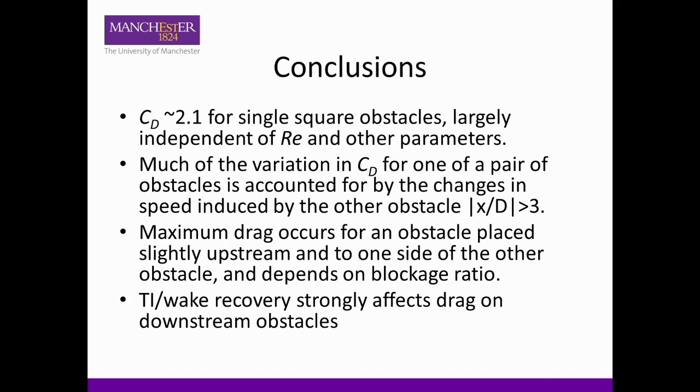Something that we haven't talked about a lot here, but I've said we're trying to simulate realistic environmental flows, and people have found this as well when they're looking at arrays of wind turbines or marine current turbines. It's important to think about how the wake recovery works, because if you get that wrong... doing numerical experiments, it's really easy to get the drag on the first obstacle right. It's very much harder to get the drag on the downstream obstacle right, and that's because of this issue, I think. That's always been a bit of a challenge. Okay.